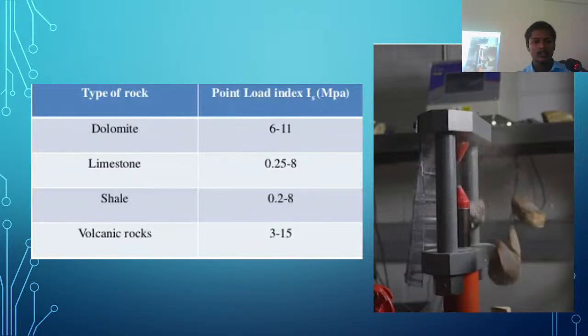in the laboratory, scientists did some lab tests, and they found some tabular data for some rocks. Dolomite can withstand 6 to 11 megapascal, limestone 0.25 to 28, shale 0.28 to 28, and volcanic rock can withstand a maximum load of 3 to 15 megapascal.